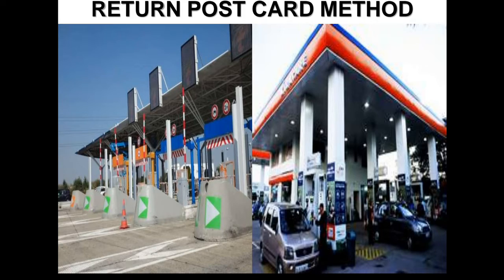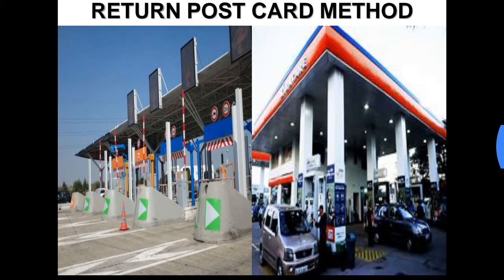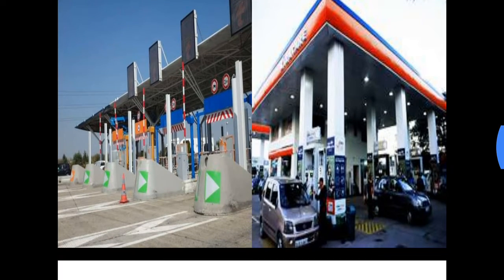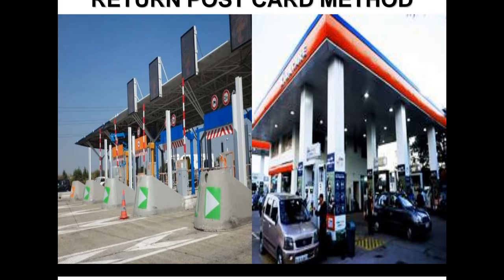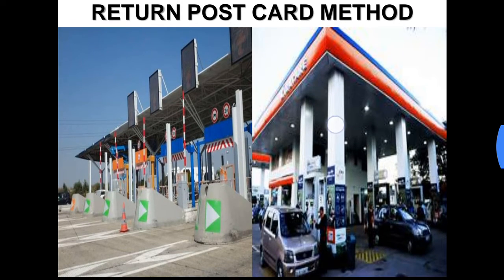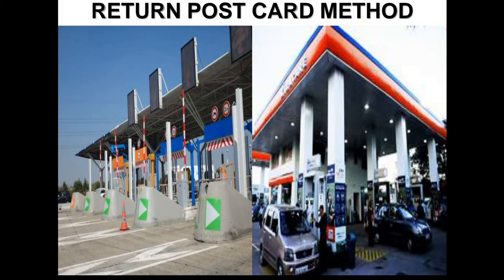Now here we prepare a questionnaire or a set of questions and write them down in a postcard, and at the places where vehicles normally stop like petrol bunks or toll booths, we distribute these postcards to the drivers, and along with the postcards we have a small gift for the driver so that he gets motivated to fill in the details and repost that postcard to the traffic department.